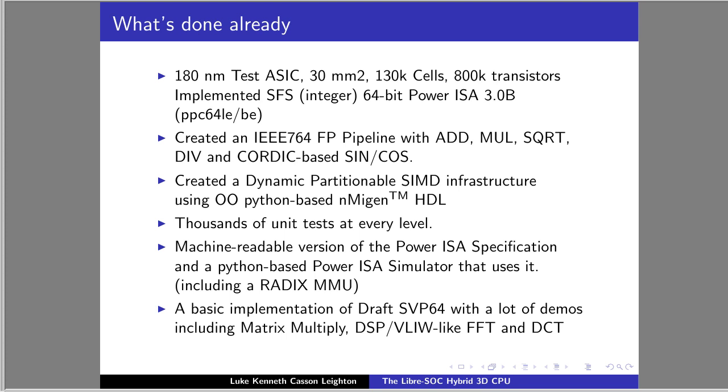And it is based around the concept of adding a for loop around scalar instructions. We do not add any vector instructions. We have added a for loop, a sub-program counter around the scalar Power ISA. Okay, that is very, very significant.